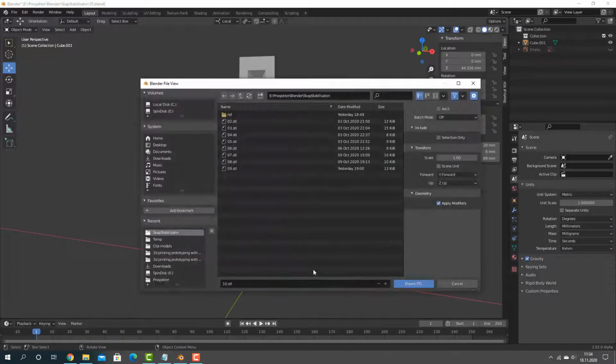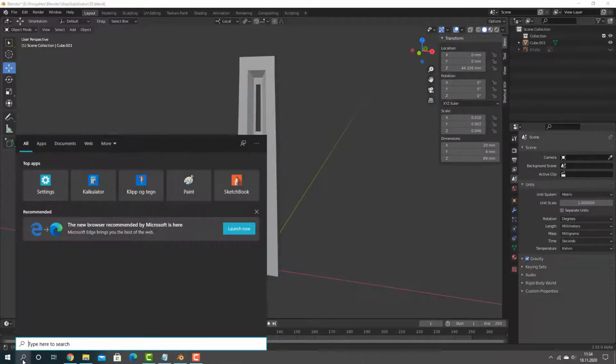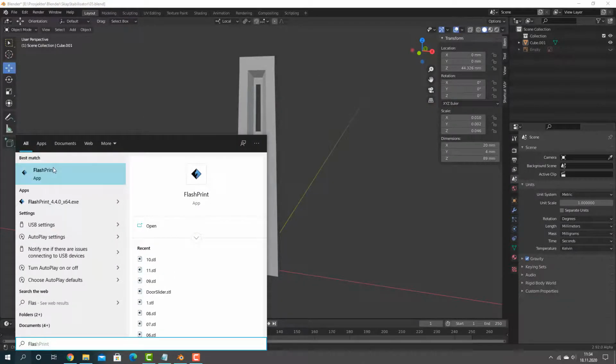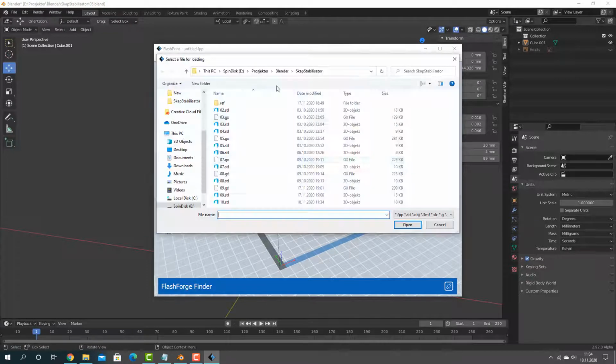Here, we will export the model out to the 3D printing software using the STL format. Note that internal Blender scale is different than the scaling factor in the 3D printing software. So if you select 1 as scale, the model will be very small and you have to scale it up manually.